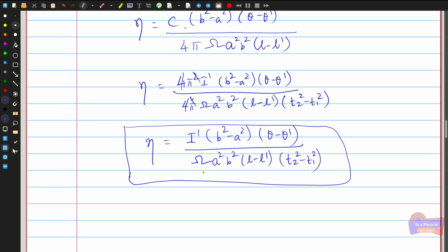One important thing in this experiment is that the speed of rotation of the outer cylinder must be kept low, some very small value. Otherwise, if the rotation is very high, the fluid flow becomes turbulent, not laminar, so that the torque is no longer proportional to the angular velocity omega. This can be avoided by rotating the outer cylinder with lower angular velocities.